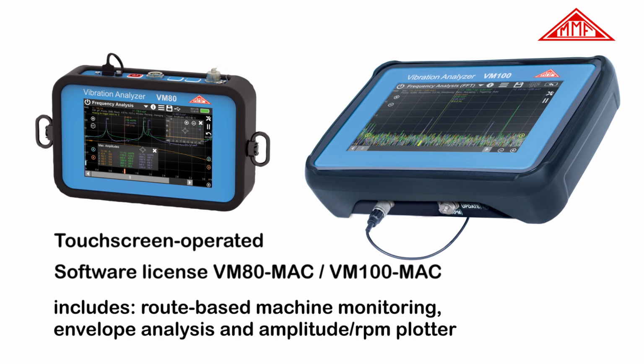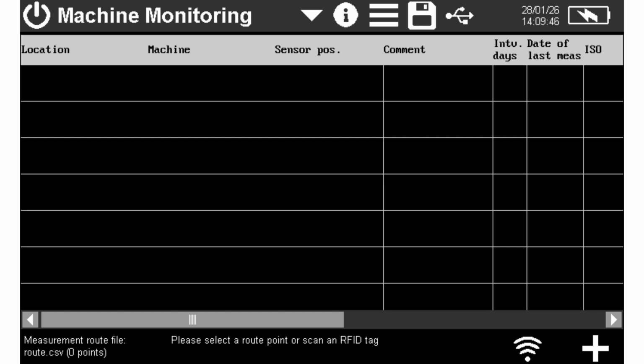This license includes 3 modules: the actual machine monitoring module for route-based measurement, the envelope analysis module, and the amplitude over RPM plotter. We begin with the route-based machine monitoring module. The measurement route table is initially empty. We will now add the first route point.